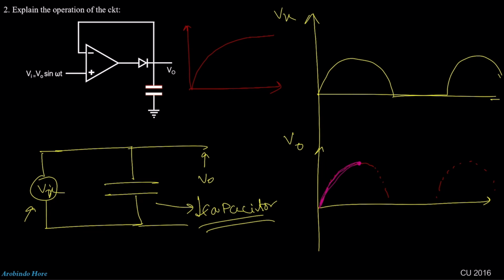Now see this. Here you can see for the capacitor in the charging cycle there is no resistance, R equal to 0, right? That means the time constant for charging is very fast, it is 0. That's why it will exactly follow the input voltage curve, okay? Now for the output, you can see the output R is infinite as there is no resistance in the output.